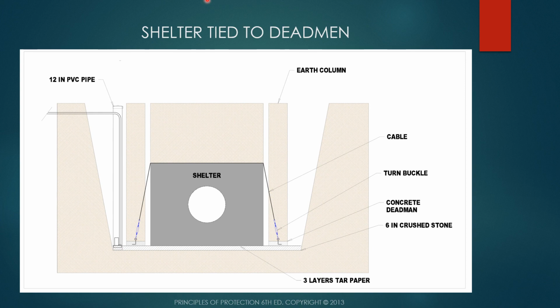So when you put a concrete slab and you tie this down, it's this weight of the earth at 70 pounds a cubic foot, this weight at 70 pounds a cubic foot, and this weight at 70 pounds a cubic foot. That is your counter hydrostatic pressure.